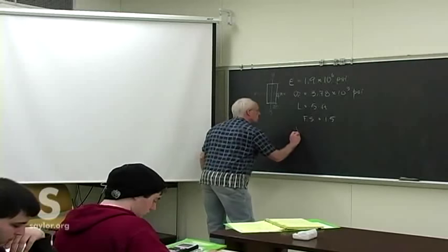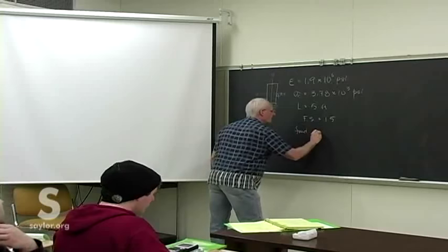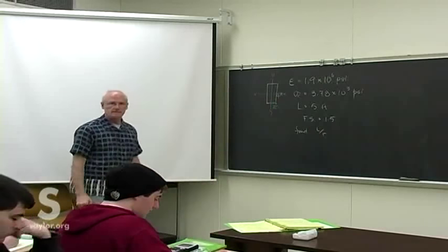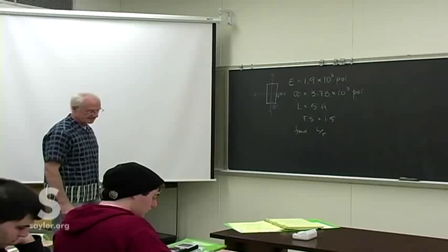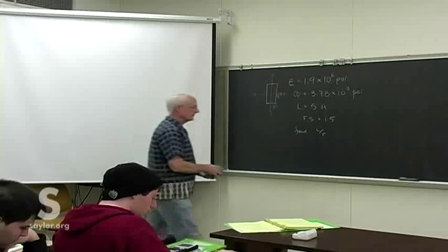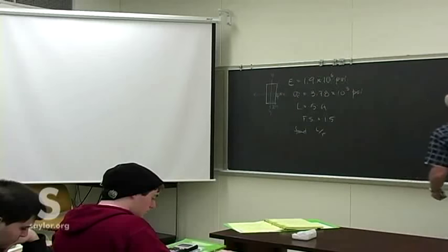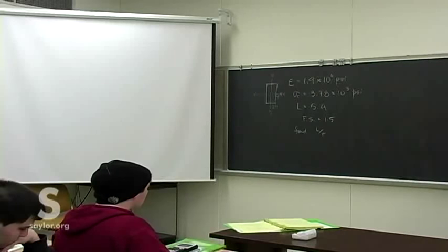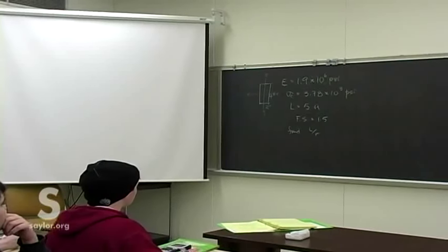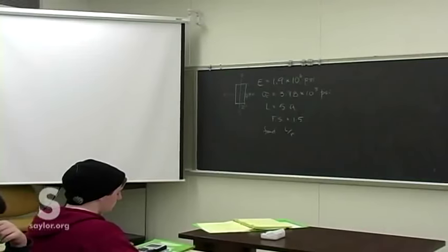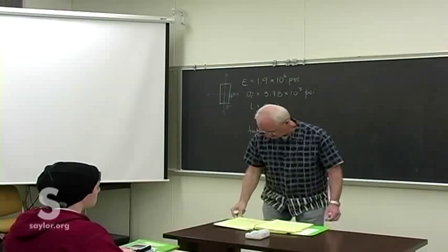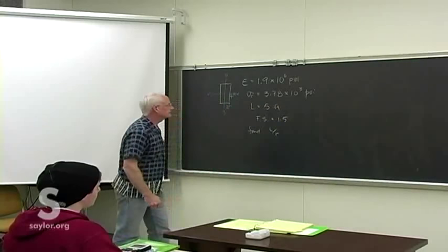All right, so find the slenderness ratio, this L over r, and then find the allowable load once we've determined that. Now the concern is that it's more likely to buckle in one direction than the other. Now experience tells us which it is, but that doesn't mean it's not something we can double check.